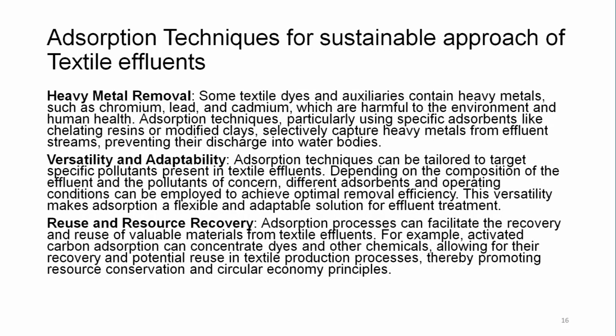The adsorption techniques, particularly using specific adsorbents like chelating resins or modified clays, selectively capture heavy metals from effluent streams, preventing their discharge into the water bodies. Versatility and adaptability. Adsorption techniques can be tailored to target specific pollutants present in textile effluent.